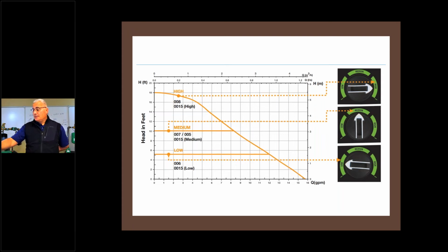And I want to point something else out to you. If I can vary my speed out to 12 GPM, we could take the universal hydronics formula, and if I can divide a BTU by 10,000 to get a GPM, I could take a GPM and multiply it by 10,000 to get a BTU. So gents, I can be varying my speed, maintaining 5 feet of head out to 120,000 BTUs. Okay? I want you to understand that. That's what that number means.